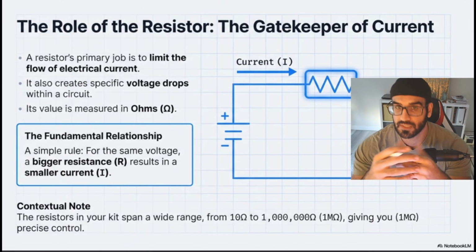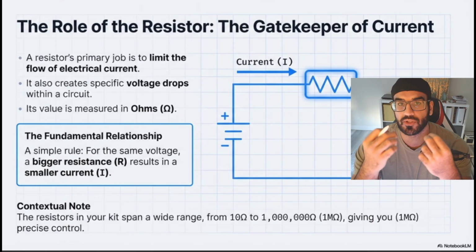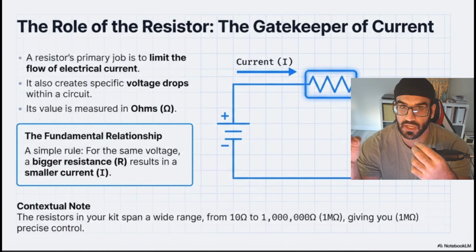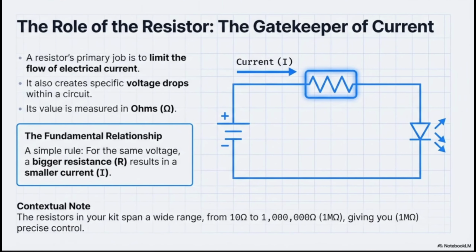And I told you that sometimes we need to control the amount of current that gets into our load. At this point, imagine that I have a circuit, and this circuit contains 3 important parts. The very first part is the source. That source should be connected to my LED or lamp in order to turn it on, right? In the meantime, I know for a fact that my LED or lamp can only handle maybe milliamps of current. What should I do? Either I have to reduce this voltage, which is sometimes impossible because I have a constant voltage, or I can put a resistance beside it.